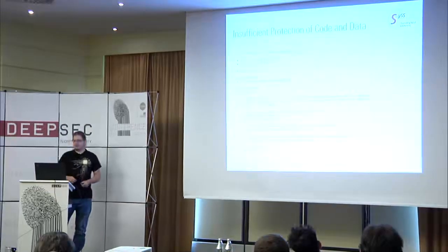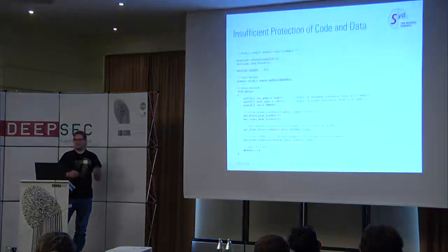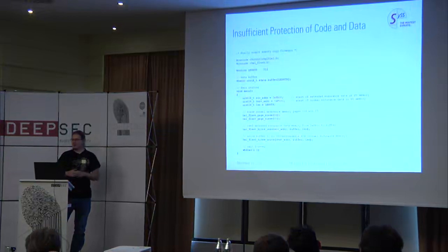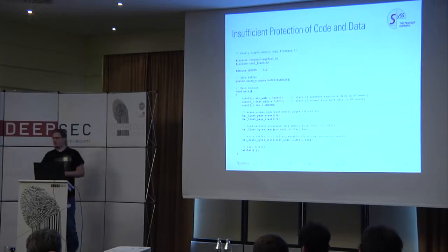So we read out the dongle, we read out the firmware, and wrote a little program to check where we can find 16 matching bytes, because it's AES 128. The key length is 16 bytes, and we were not able to find such bytes. So we remembered, okay, there's a section in the non-volatile memory we cannot read using SPI. So my friend and colleague Matthias wrote this little piece of software. It's actually a program for the NRF24 chip.